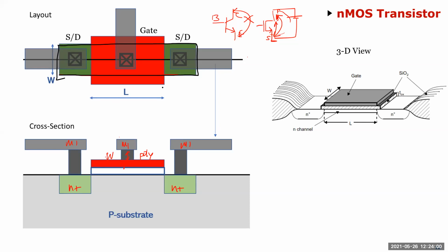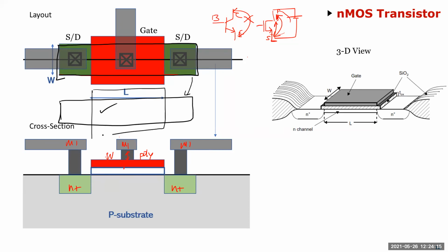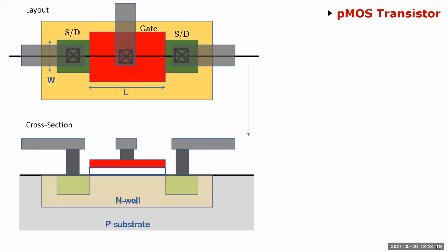As I was showing yesterday, when the foundry takes it, they will have the diffusion mask, which will be a complete mask, and they'll do all the implant and everything using this mask. And then on top of this, you put the gate. The overlaps and all that we'll talk about in detail when we're talking about layout.